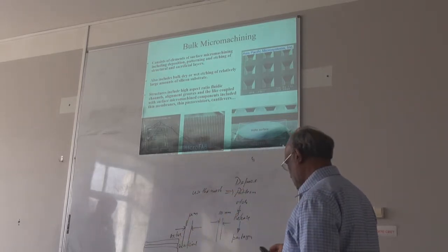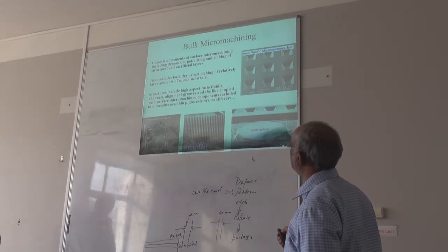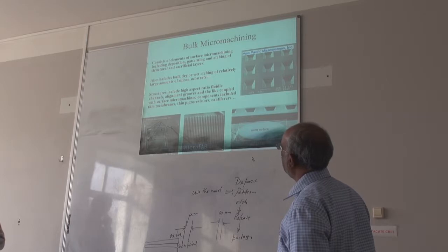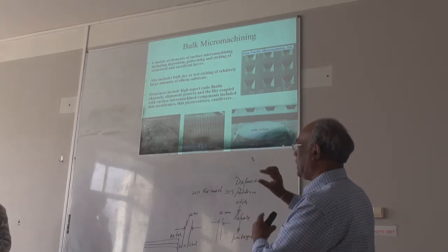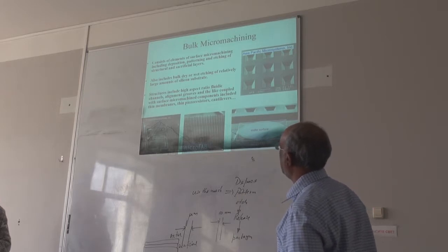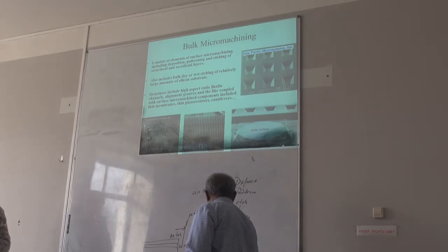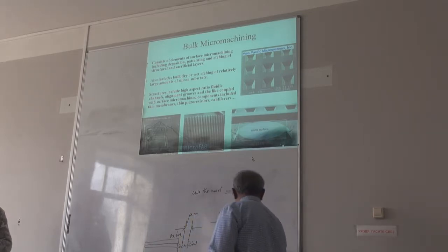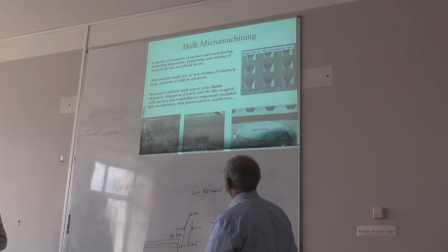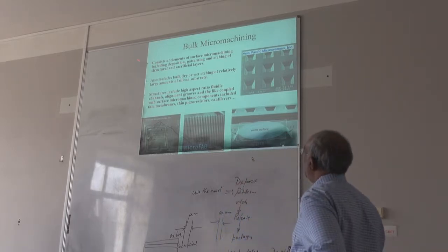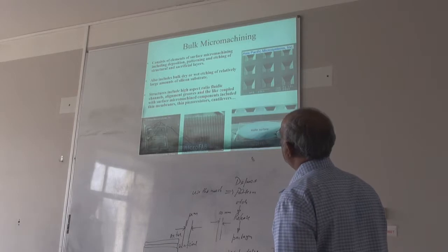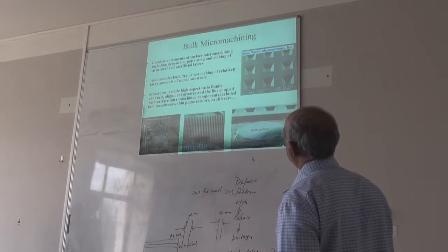But in this micromachining, an important thing is they involve a lot of dry and wet etching for large substrates. So big substrates and thick substrates. We'll talk about all these things: wet etching, which is more like chemical, then you can use dry etching, mostly using plasma. But an important thing is these structures include very high aspect ratio fluidic channels.